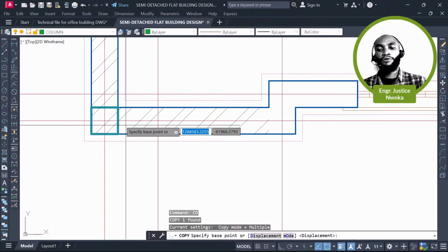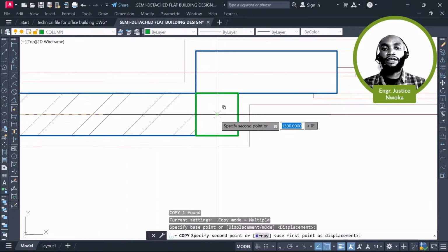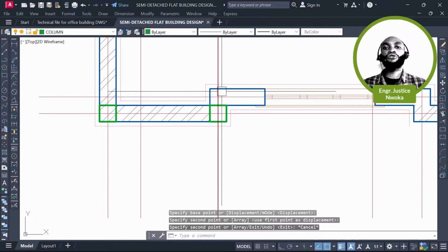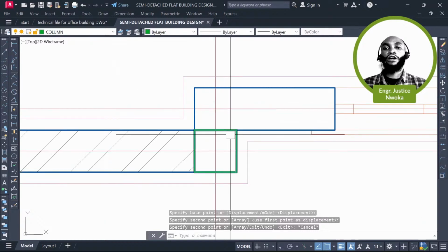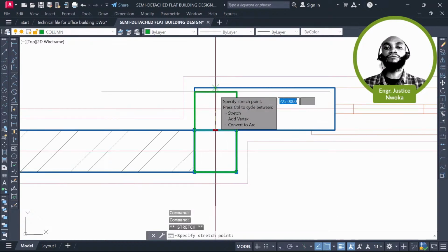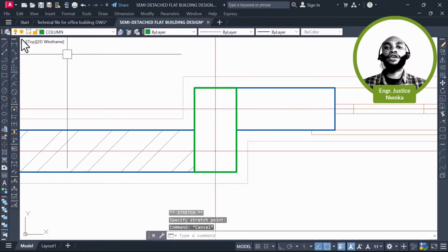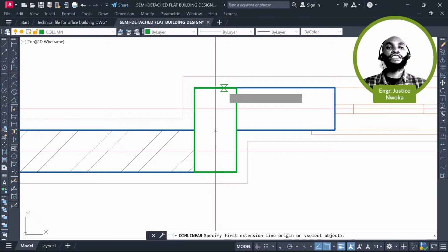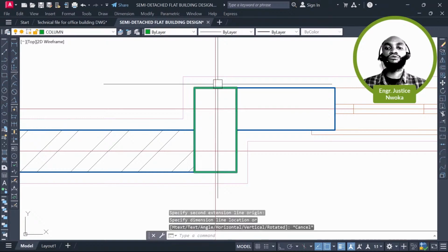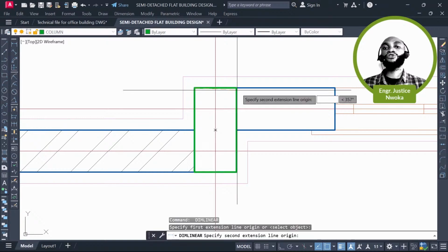Now if I come to this place to place my column here, just to be able to achieve this shape, I don't want a cantilever beam coming out because this is very, very small. So instead of that, I'll just throw a 450 column here. If I check this, from here to here is 450 by 225, because I want to achieve this shape perfectly.